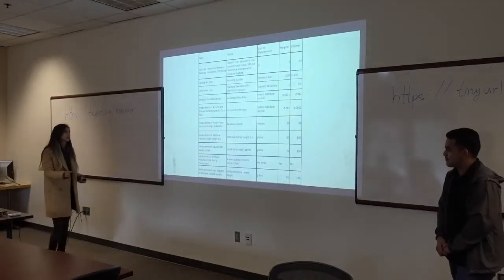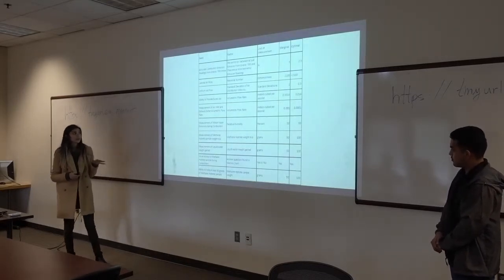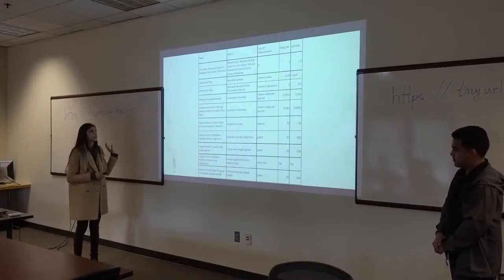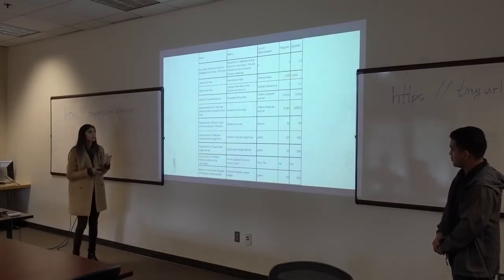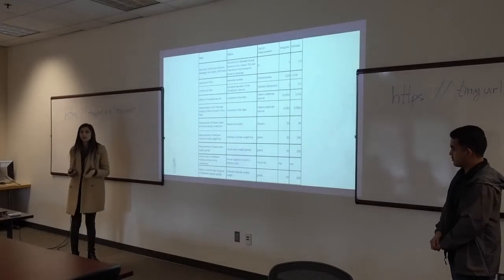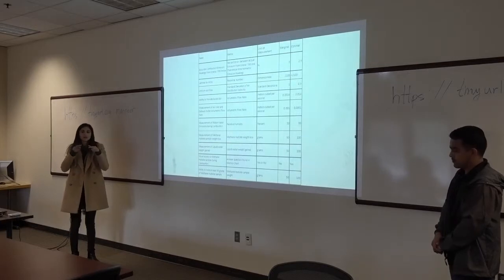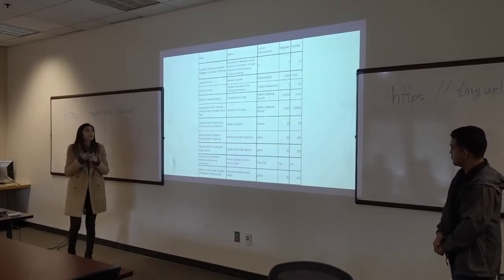So to touch on our experimentation, from last quarter, we had a needs metric matrix where we had certain criteria that we needed to fulfill for this experimentation. The first one that I want to touch on is laminar airflow. We looked at the Reynolds number, and we have to make sure that it's less than 2100. This is important for our chamber because in order to get accurate emissions readings, we need laminar flow, so that the airflow could be stagnant, and all the emissions could be towards the top where the probe can measure it.